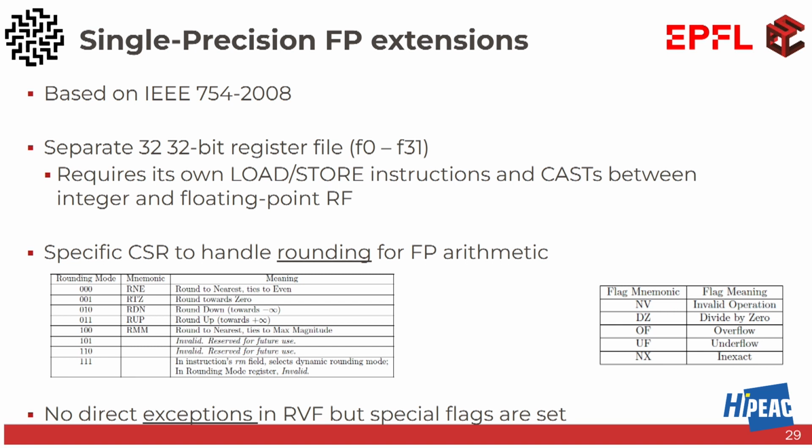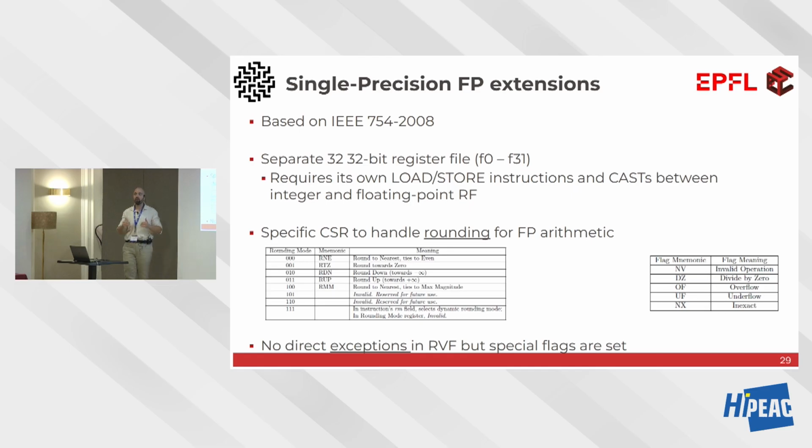So in that case, your application will use the normal load and store instructions to move a floating point number to the register file. So now that the register file contains both integer and floating point operands, how does my CPU know whether it should do an addition with the integer hardware or with the floating point hardware?